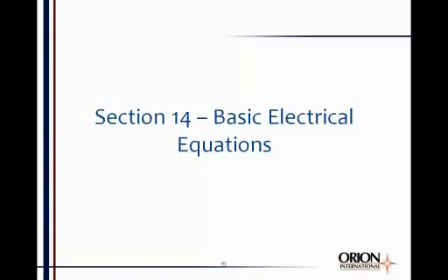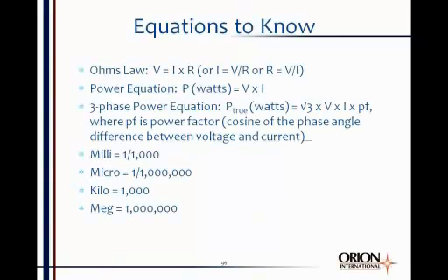Now, this last section here I want to talk about is some basic electrical equations. I think you'll find some of these useful just as a reminder, okay? First of all, Ohm's law. Ohm's law in its basic form says voltage equals current times resistance. And you can convert that equation to say I is equal to V over R, or R is equal to V over I. And Ohm's law applies to both AC and DC.